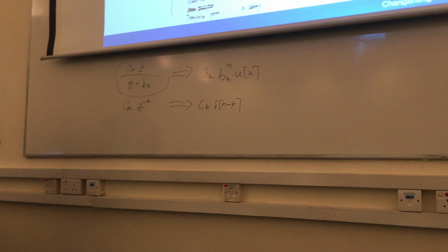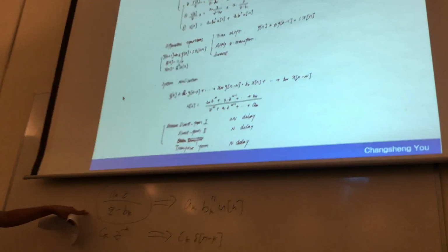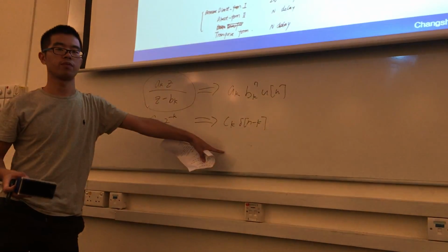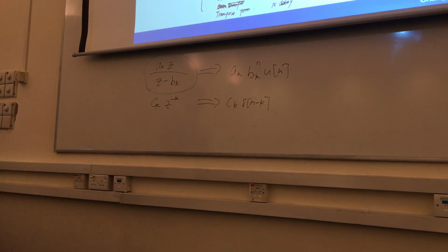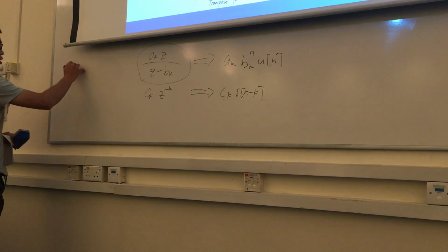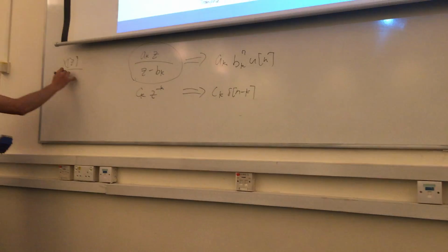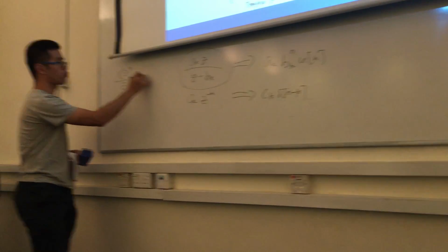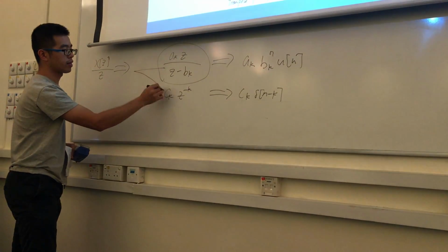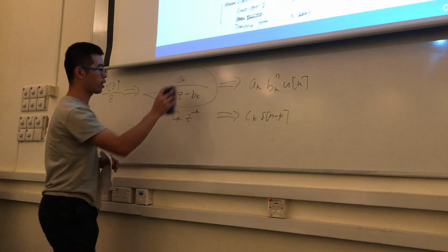So in these topics, we want to decompose the inverse transform into this kind of form, a summation of this kind of forms. And then we can easily write down the inverse transform. All right? So an easy way is, first step, we write it down this way. We divide Xz by z, and then we express it by this kind of form. This one and this one. Sorry, it should be this one, this one.